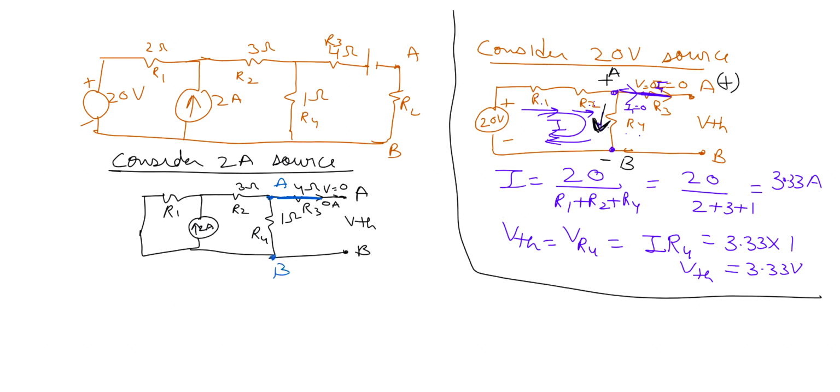Now if you see, this 2 ampere current is divided here and then going this way. So this is I1 and this is I2. So the 2 ampere current is split into I1 and I2. Now you can see that R1 is in parallel to the R2 and R4 resistors. So basically, if I redraw, this is 2 ampere, this is R1, and this one is R2, R4 combined, because I2 current flows through R2 and I2 current flows through R4. So R2 and R4 are in series.